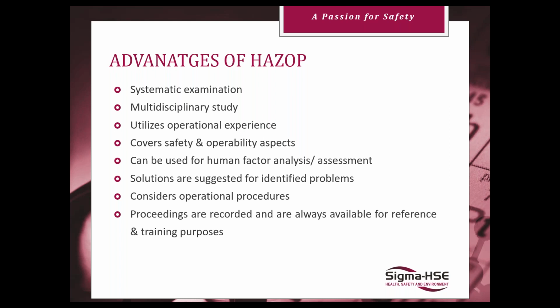So you're not just looking at could this cause an injury, but what would happen if we close this valve and it causes material to freeze in the line, and now you have a clean out of 4 days. It doesn't hurt anyone, which is good, but now you're looking at a loss of production, which is a loss of income. Is that a concern that you want to address as well?